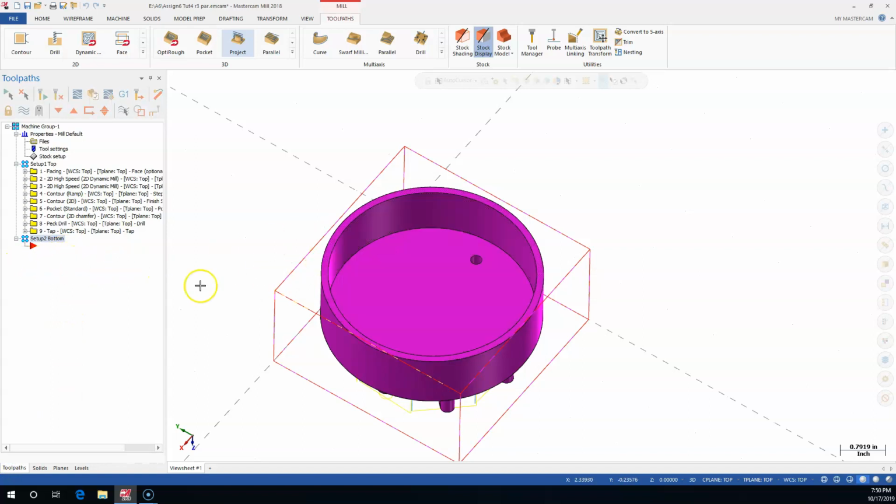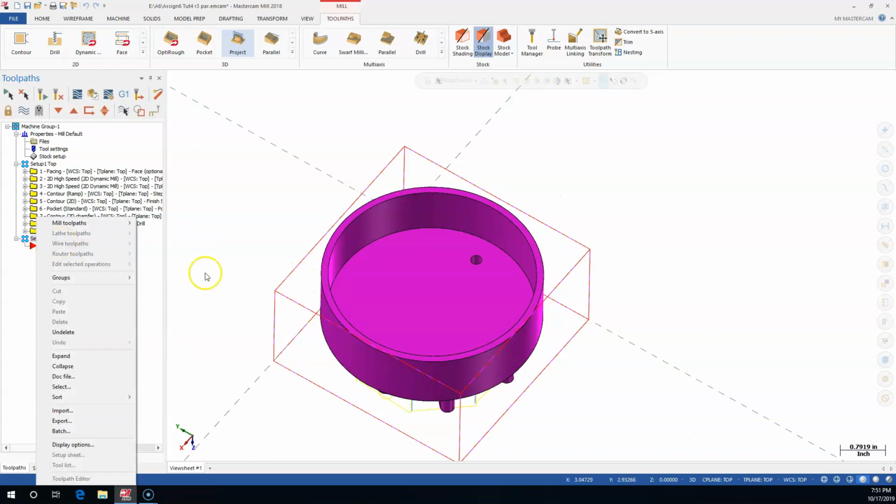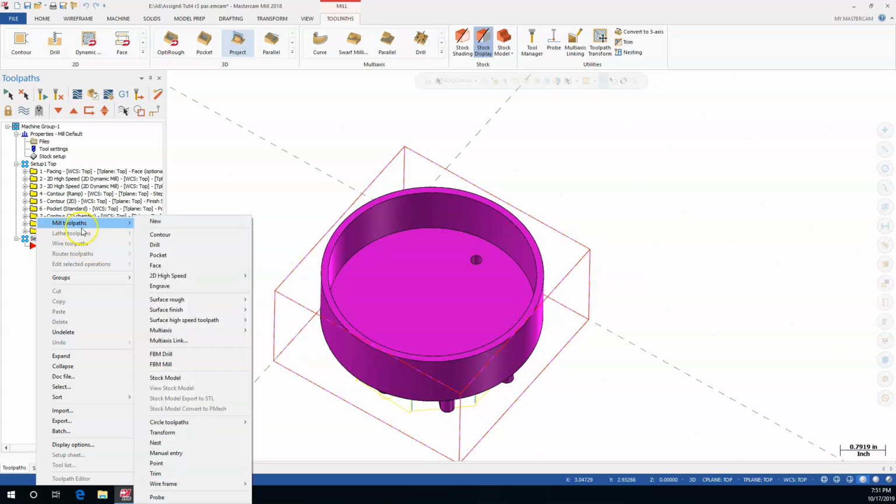Alright, so our facing operation, those little tabs that are left in the corners, we're just going to bandsaw those off, so I'll have kind of a rough surface, but I should be able to start at the outside and work my way in. Thing with the acrylic is we have a little bit of chipping, fracturing to be concerned with along this leading edge, so we'll have to address that accordingly. Hopefully the 10,000ths that we went past will be enough that it won't break out.